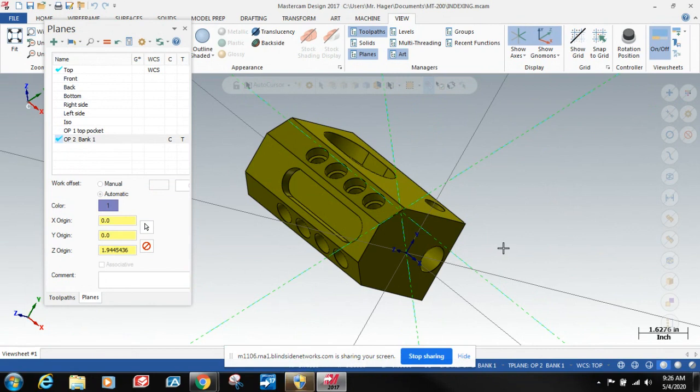I just tried it again. It's really weird. What it's doing is putting it inside the part, and for some reason it looks like it's changing the Z. Maybe did you click on a hole? No, I didn't click on a hole. I clicked on the flat part towards the back of the part. You moved to 3 inches because it comes in with X at 3 inches, but then I was moving it out to 0 to the face. Yeah, X0, right? And then when I do Y0, it puts it inside the part for some reason.